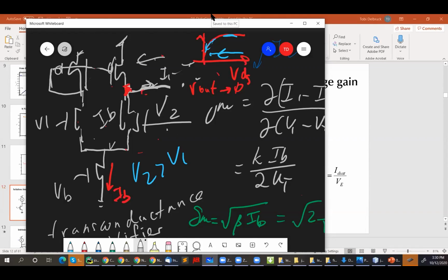Because V2 cannot conduct any current through M2. Yeah, right. So it's actually very strange, because right now the current is flowing this way, and that's because V is less than V2. But then, if you now have, say, V out close to ground, that's actually kind of a strange thing, because what does this mean? It means that now my VDS, my drain and source are flipped around, because this voltage will be at a lower voltage than the V. So that implies that the current is flowing this way.